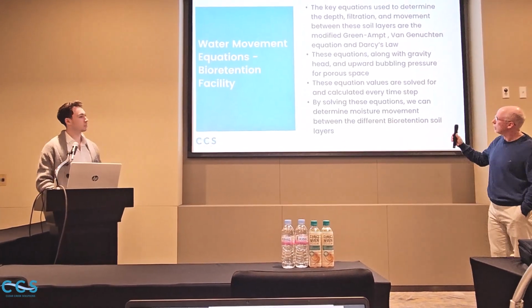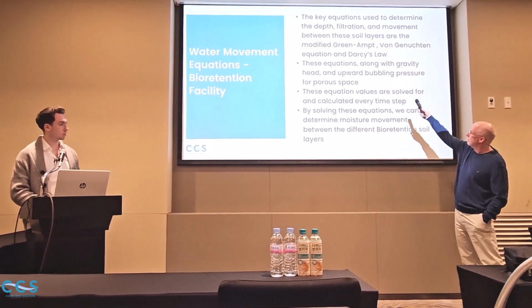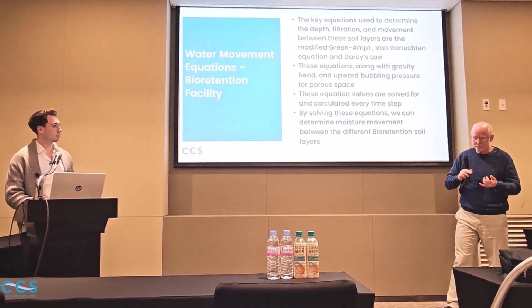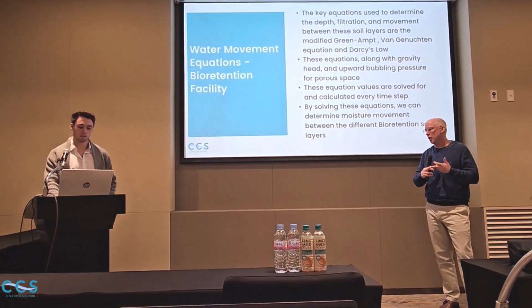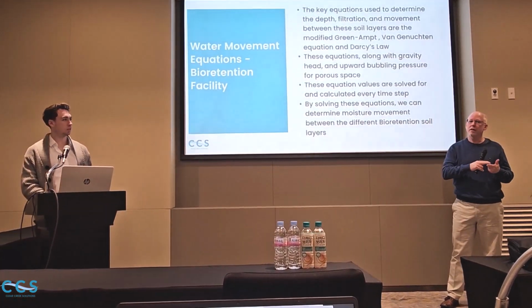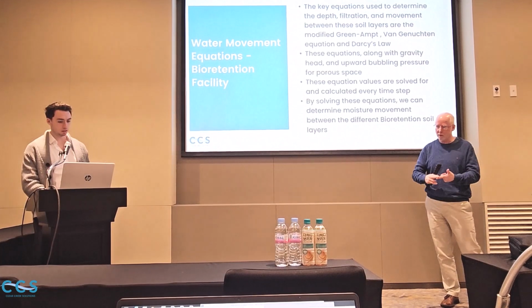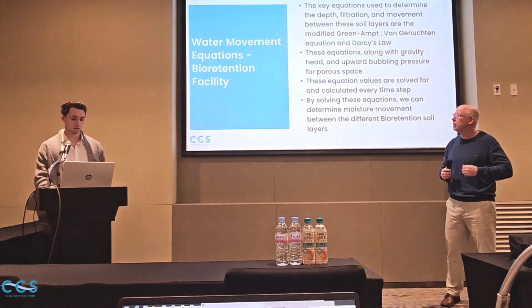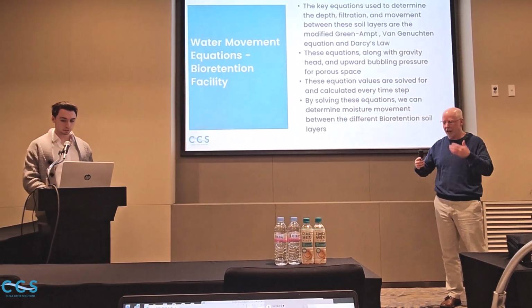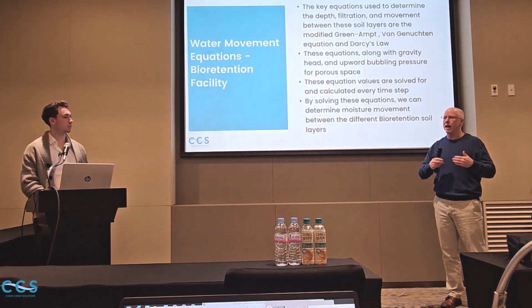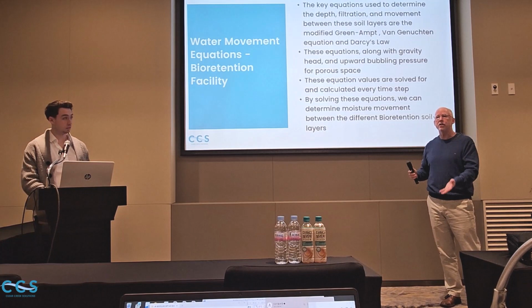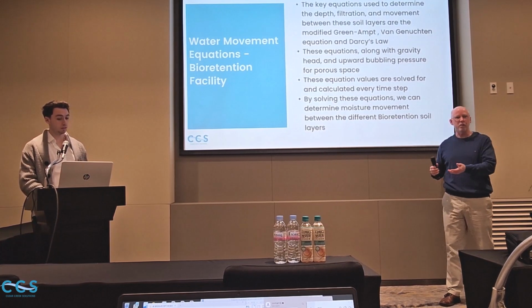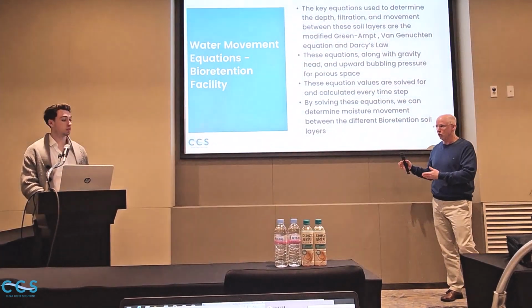So we deal with these different factors: the head, the bubbling pressure, the soil moisture, the saturated conductivity, the hydraulic conductivity. All of these are tracked inside the program so that over 60 or 70 years, it'll change the conditions in the bioretention unit to match the real world.